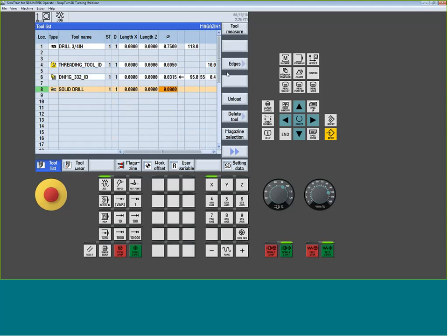So first of all, let's say this is going to be a 1-inch tool. We'll give it a 1-inch tool. You notice it doesn't give me a tip angle now, where I had a tip angle up top. That's because this is a flat bottom style insert drill.